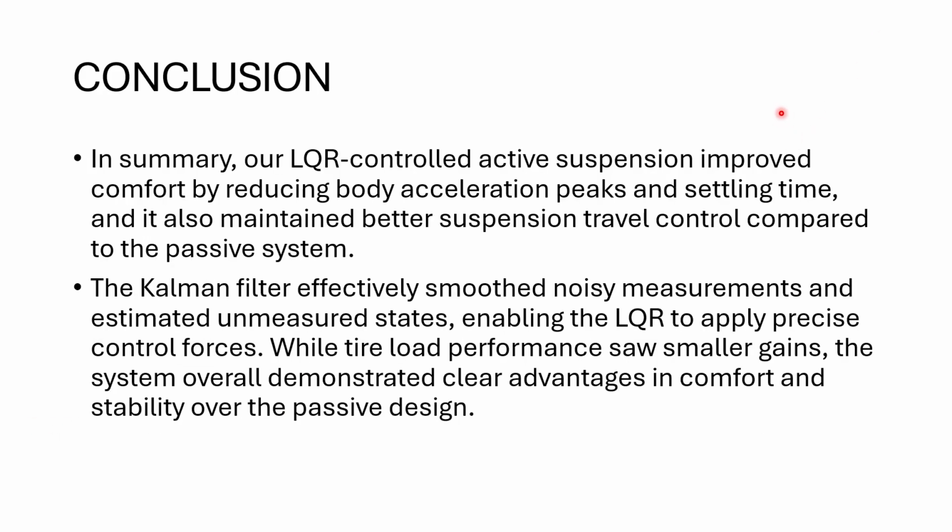In conclusion, I learned that the difference between active and passive suspension is very minimal, and this explained why most cars use passive suspension. Our LQR controlled active suspension improved comfort by reducing body acceleration peaks and settling time, and it also maintained better suspension travel control compared to the passive system.